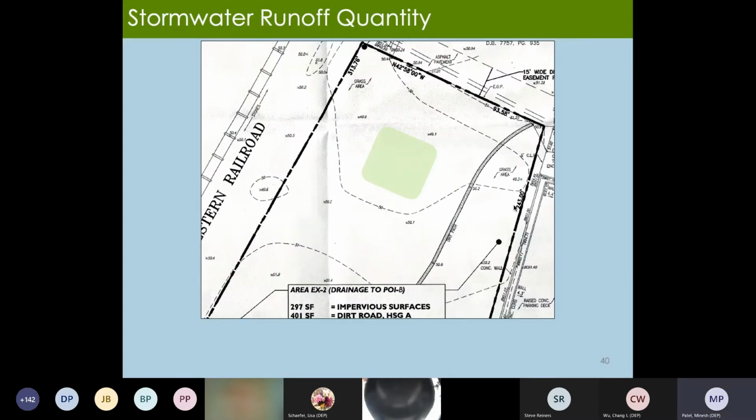So on the same example site that was shown before, there was a 6-inch deep ponded area within the shape depicted. This was ignored, and the basin was made significantly larger than what was needed. If there are any questions as to whether areas of ponding exist on site and it cannot be determined from the photos of the site, it may be necessary for the reviewer to again go and visit the site in person.